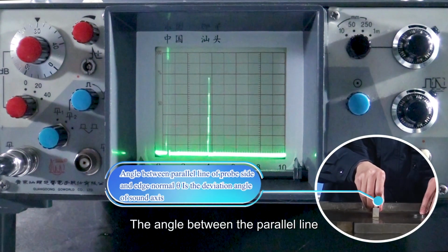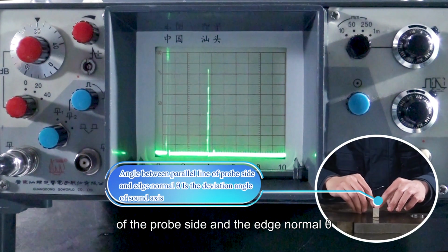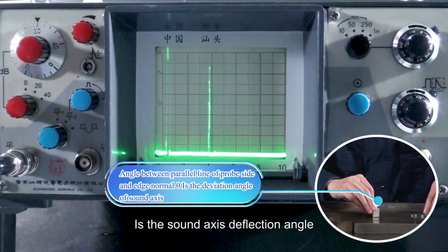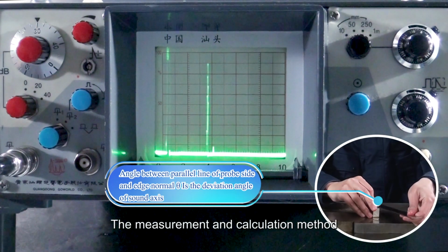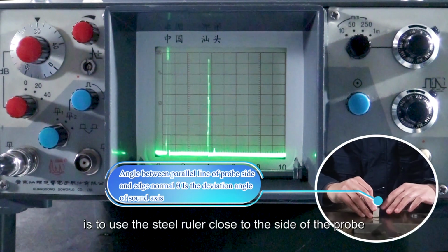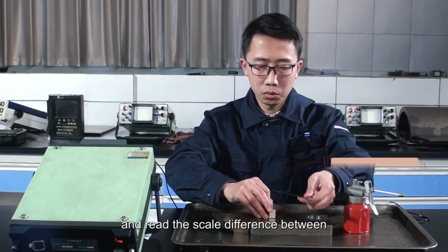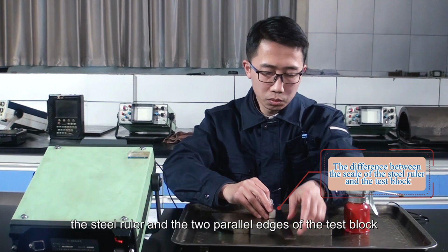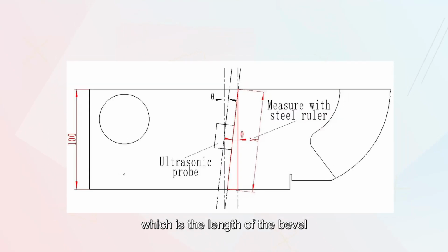The angle theta between the parallel line of the probe side and the edge normal is the sound axis deflection angle. The measurement and calculation method is to place a steel ruler close to the side of the probe and read the scale difference between the steel ruler and the two parallel edges of the test block, which is the length of the bevel of the red triangle shown in the figure.